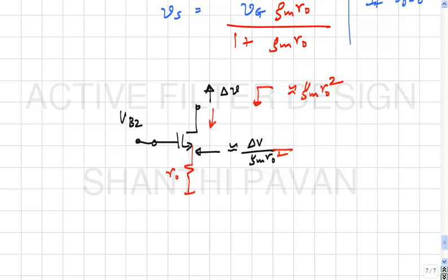Okay, so this is the intuition behind why a cascode helps increase the output impedance, because this voltage can be varying wildly, but the variations at the source will be attenuated by approximately gm ro. Correct? So the lousy current source you had before is seeing only a much smaller variation, which means that effectively its output impedance is getting multiplied by gm ro. Does it make sense? In fact, all this stuff was there in one of the EC201 tutorials, which of course none of you have done. So, all right.